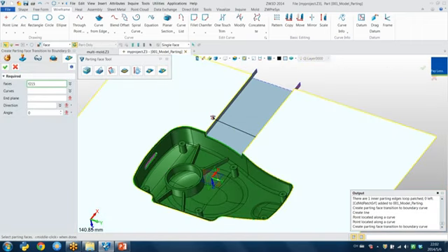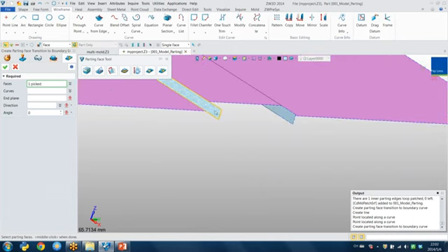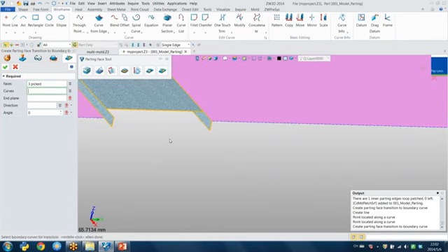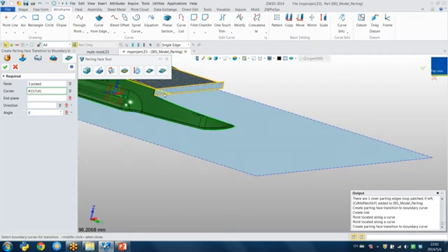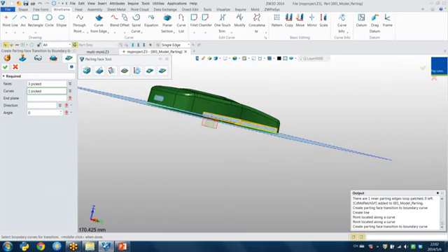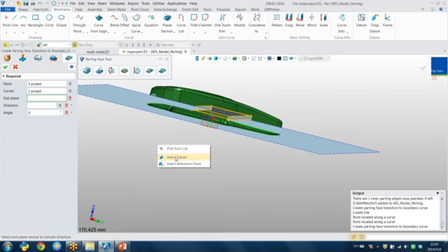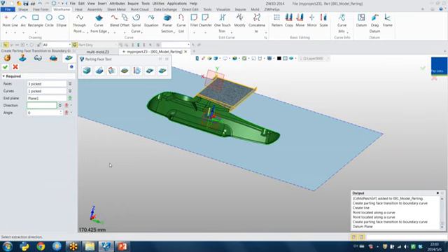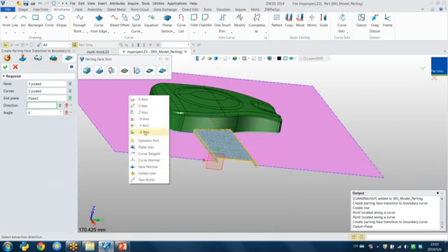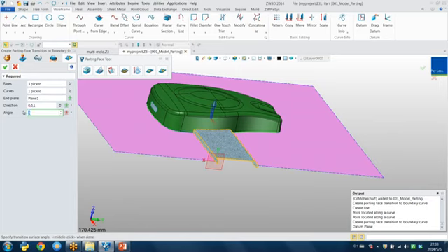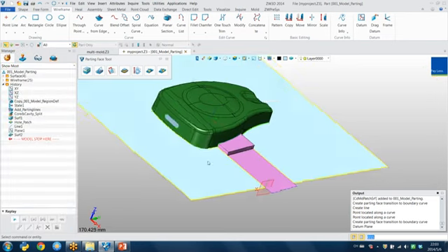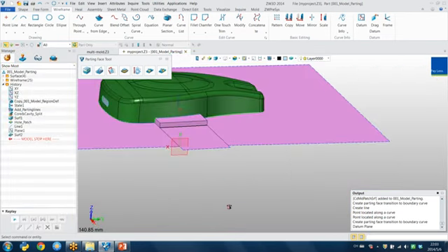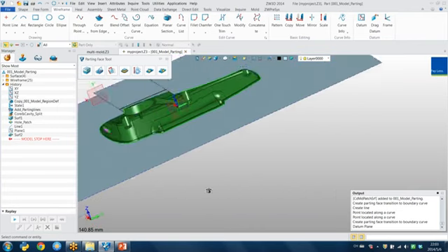Then I choose the face 1, 2, 3, and then select the curve, and end plan. Right click to insert a datum. And direction is Z-axis. So I can also set the draft angle. So set 5, press OK. So you can find it will correct and change the parting surface like that.